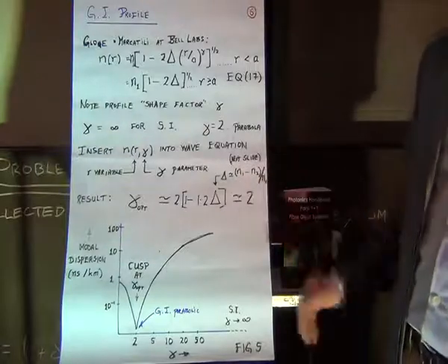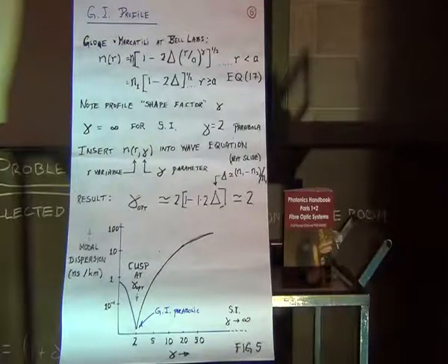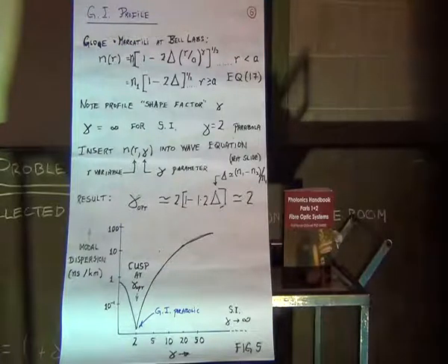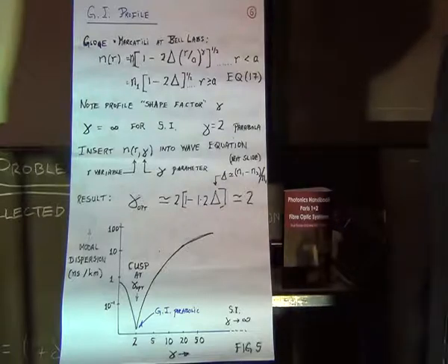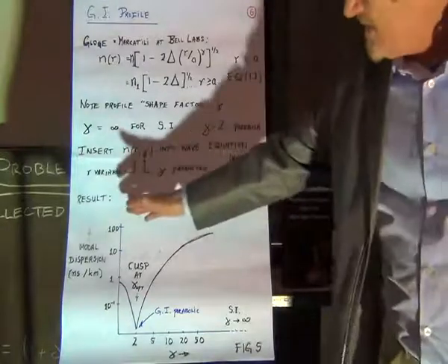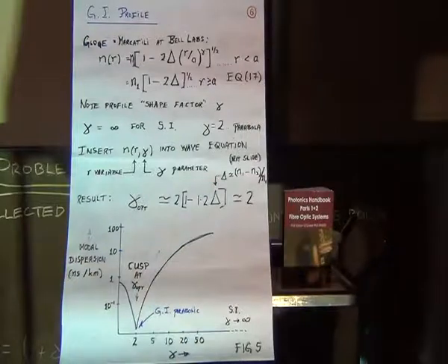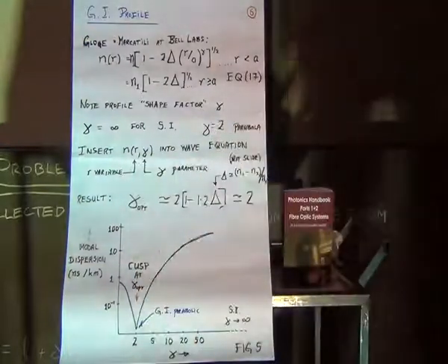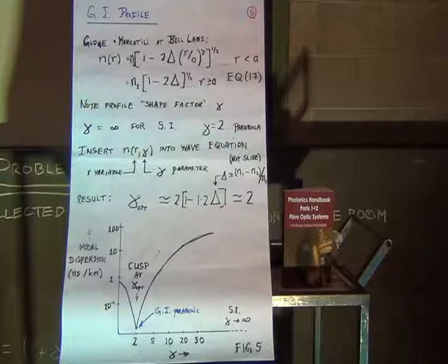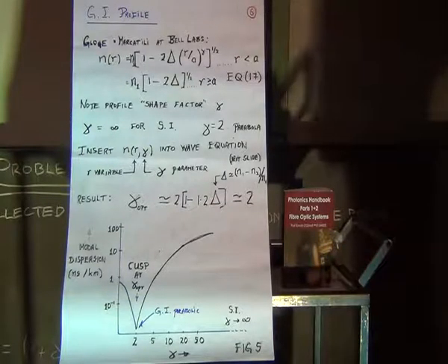by this time, the fibres that were being installed in places like New York City and San Francisco and beginning to be installed in places like Dublin and London would have been step index fibre. And these guys took a look at their results and they said, my God, there's a factor difference of 10,000 or even more, between 10 and 100,000 if I use graded index parabolic fibre. Straight away, if I can grow that kind of fibre, my bandwidth distance product increases by up to 100,000.